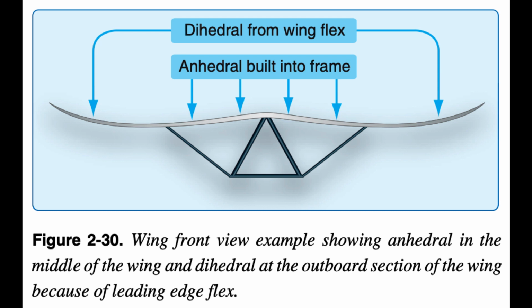Therefore, a balance between the stability and the instability is achieved through anhedral plus other important wing design features such as nose angle, twist, and airfoil shape from root to tip. An aerodynamic characteristic of swept wings is an effective dihedral based on the sweep of the wing and angle of attack.